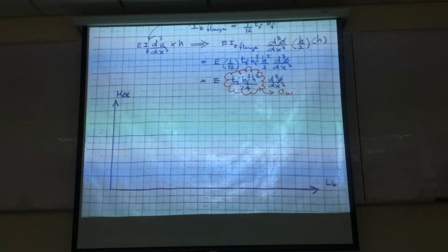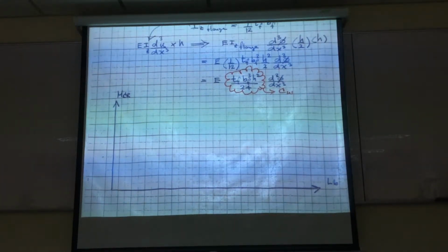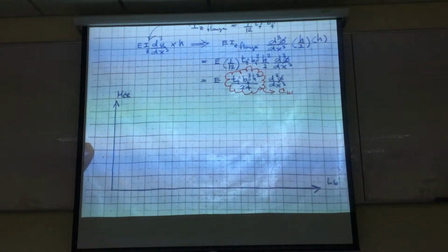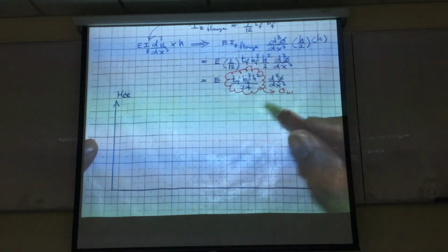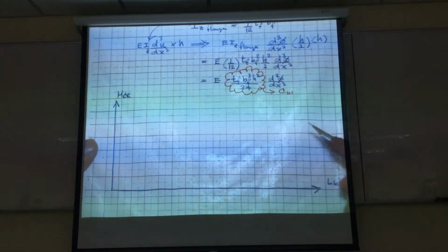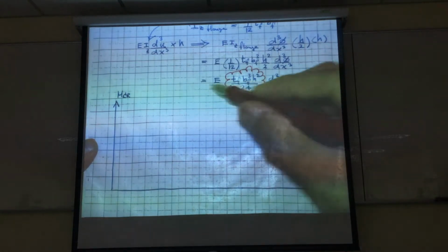Okay, the segment is unbraced. First of all, you have something pretty much like the column. So you'll be having the elastic buckling, and then inelastic lateral torsional buckling, and when the L_b is super short, you'll be able to develop the plastic moment. Okay, so you have 3 steps.